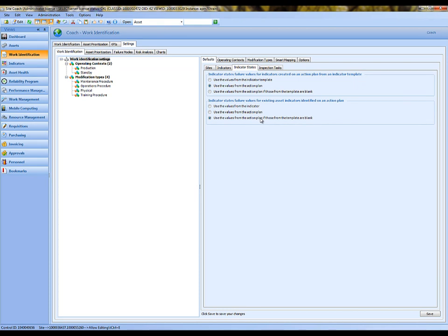The implementer will then review the failure information for each state and select the most likely or frequently occurring failure mode to use when generating the automatic failure record. This is often seen with things like vibration analysis or other broad predictive maintenance inspection technologies, because they can detect dozens of specific failure modes, such as imbalance, misalignment, flat spotting, soft foot, etc.